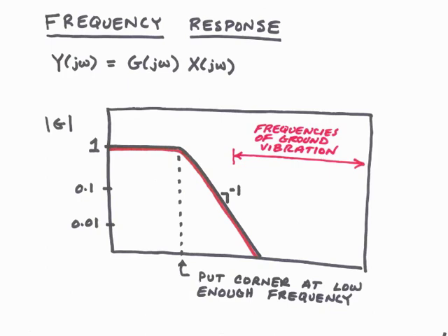The trickiness here to doing the vibration isolation table problem is to try to get the corner frequency low enough, because ground vibration can be coming in at fairly low frequencies, especially the vibration that's coming from, say, cars driving by or doors closing. So what we need to do is have that corner frequency quite low. Now think about the way to achieve that.